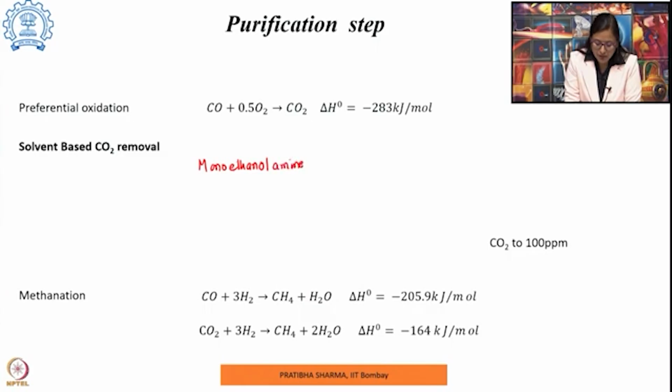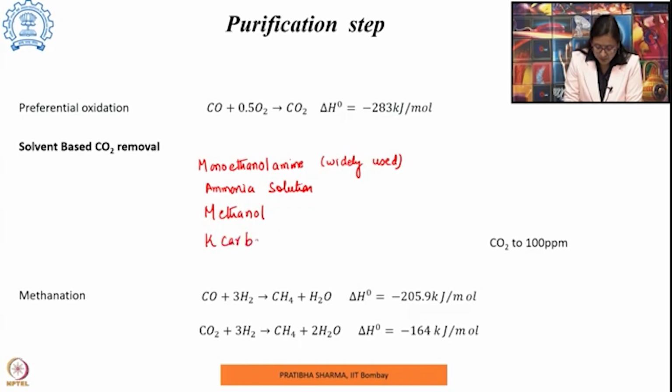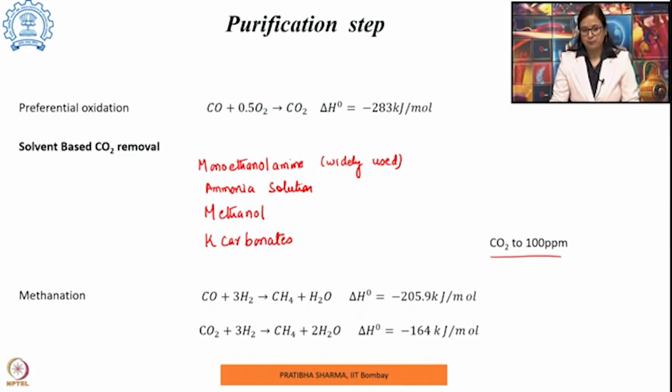This is the most widely being used. Ammonia solution, methanol, potassium carbonates. There are many solvents which are available which absorb carbon dioxide to reduce the carbon dioxide content in the product to about 100 ppm.